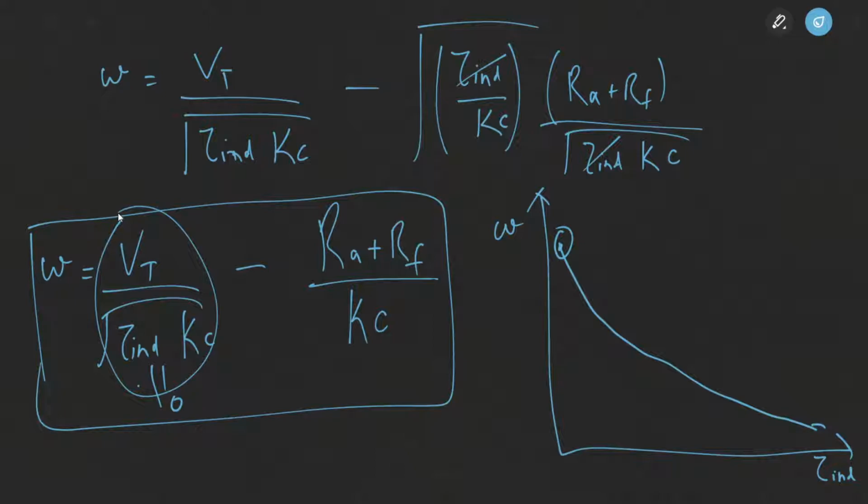So for a DC series motor, this is very important here: DC series motor, never run it unloaded. Fine.